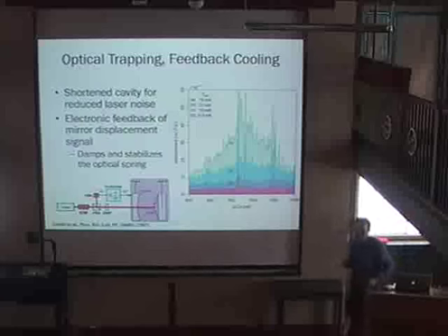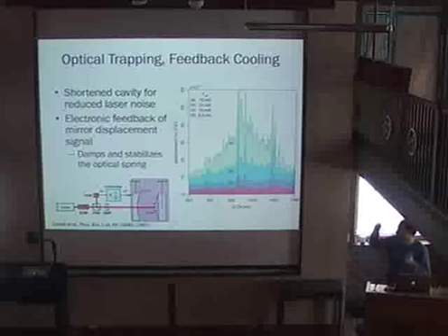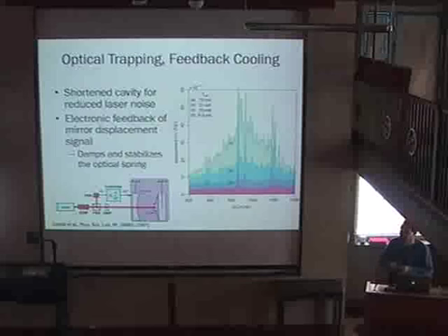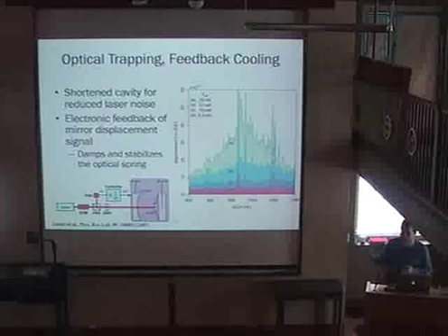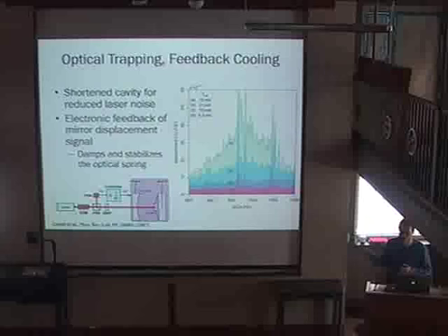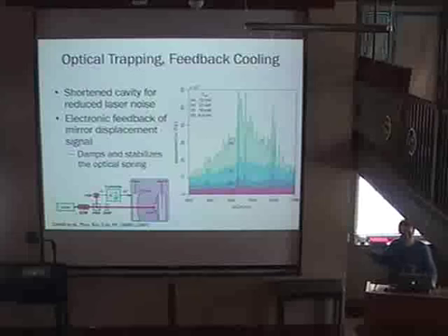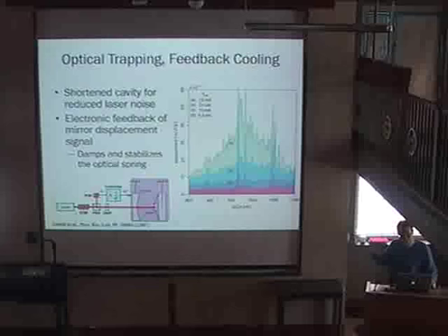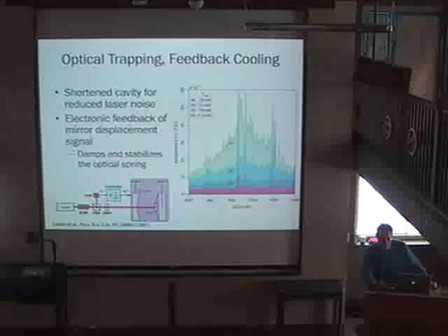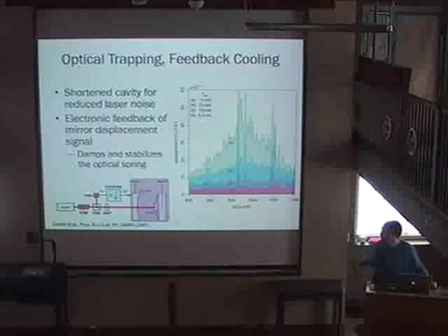Okay. Well, I think one reason why they get more ragged is because the displacement scale has gotten a lot smaller. So we're seeing more lines and other environmental lines in the system. The reason why they look less and less like a Lorentzian is because we are damping down the lowest curve here. We've damped it to a Q of around 2. So the Lorentzian just becomes very flat. It's now the same as the mechanical oscillator response function. If I ignore the really low frequency part, here I'm basically seeing a very damped mechanical oscillator. Yes.